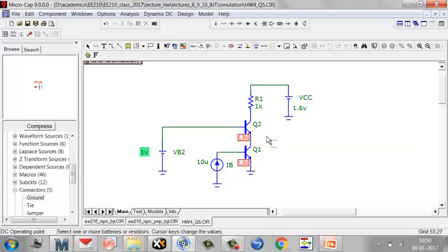So what it is saying is you may be making assumptions, but then when you actually go and simulate, you may find that things are not working, and in real life, you'll have to go and make some corrections, especially if you're pushing the boundary. We went right up to 0.2, and it's not fair to go right up to 0.2. We know that the transistor is already very close to saturation. So 0.3 was better, and with that, things are fine here. All right. Okay. So let's stop here.